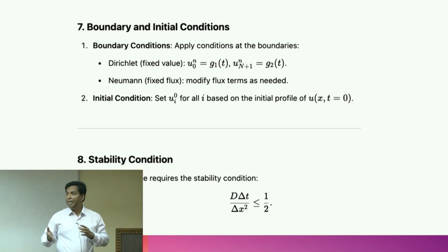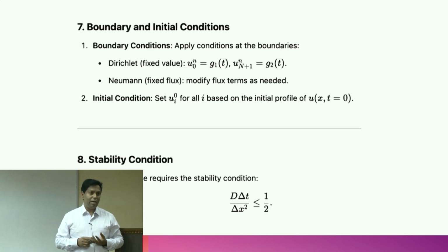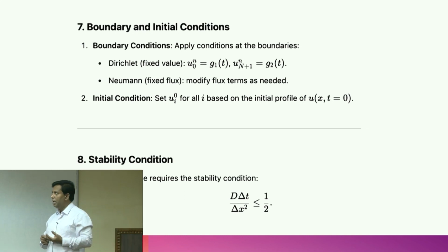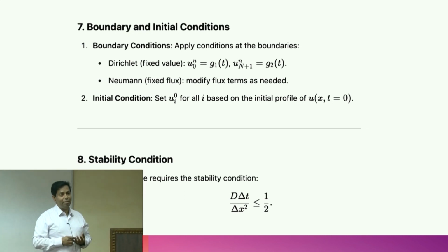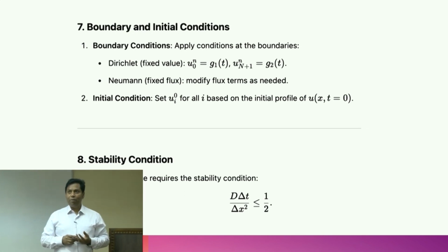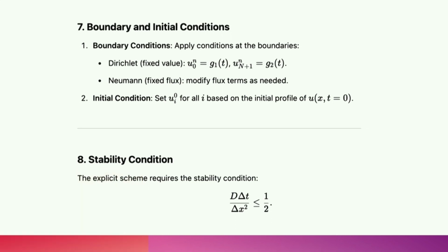When you define any problem to solve using CFD, at first you have to think about the boundary. How can you deal with the boundary? A lot of methods are available, but they have a lot of issues with the boundary. How do we set up the boundary condition? For example, the mesh-free particle method and the lattice Boltzmann method have a lot of issues with the boundary. But the finite volume method is the perfect one because it can handle the boundary very, very well.